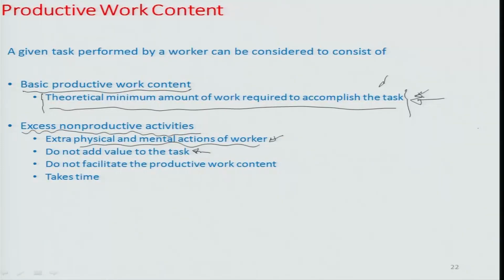You have to really identify those tasks which do not add value to the particular car. For example, in some of the older car assemblies there is this concept of dents which come on the car doors, and in order to prevent the dents there are door covers used from the beginning station. The moment the painted body comes and is laid over a slat conveyor, covers are added to all 4 doors, so that it avoids any dents or impacts during the assembly process which may otherwise happen if the cover is absent.